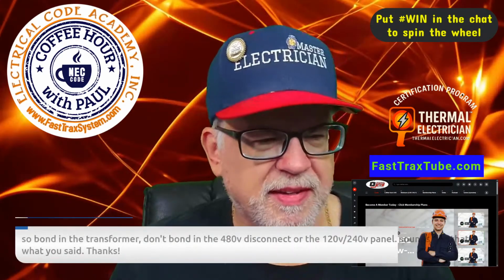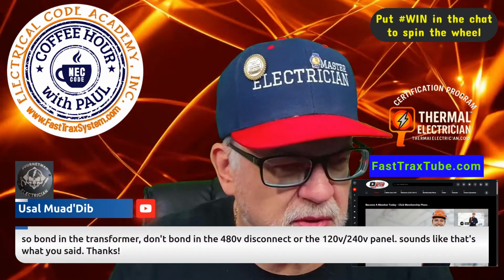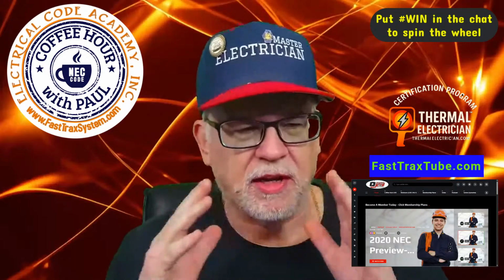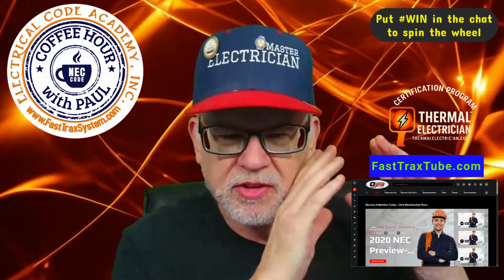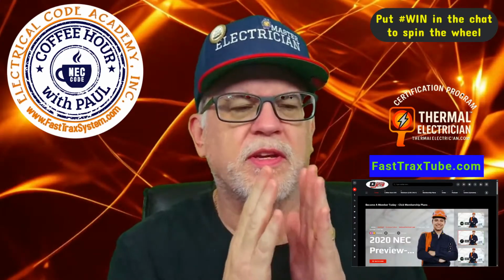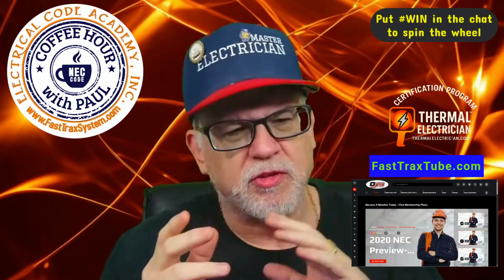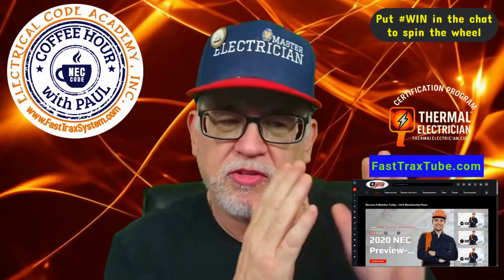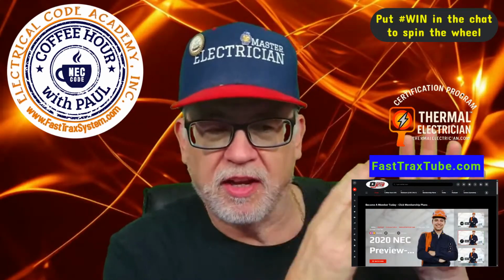All right, so you want to take today as a chance to ask all these questions here. To bond the transformer, don't bond the disconnect. Again, it seems like you're confused. Transformers have a primary side disconnect that's supplied from the panel to that disconnect, right? You treat that as you would anything else. You don't do case to neutral connections on anything downstream of the service. That disconnect for the transformer is on the primary side, supplied by the service or feeder equipment. There's a separation there. Your equipment grounds do not connect to your neutrals, okay? So that is done as normal.